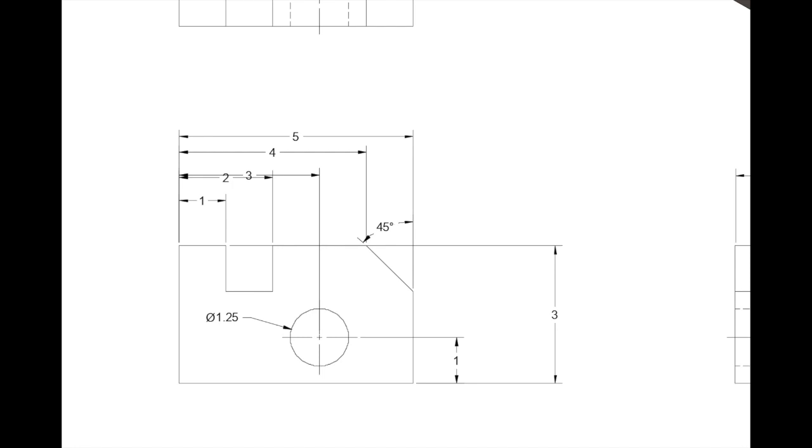All right, coming back through, I have all of my overall dimensions done. I have all of my location dimensions. And then I have the size dimensions of each of these features, except I don't have the size of the depth of this notch. So I would need to show how deep that actually comes into the shape. So always go back over and look through if you have everything. If you couldn't 3D model or manufacture this, you must be missing something.